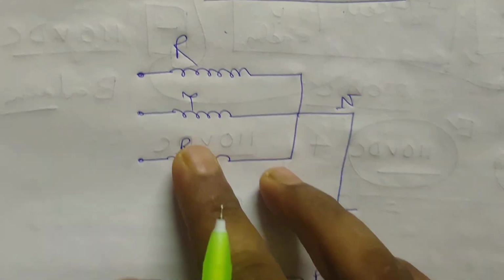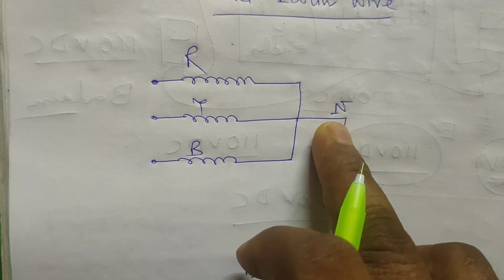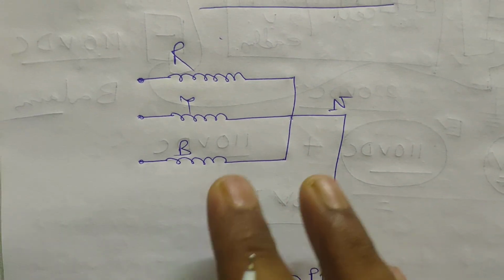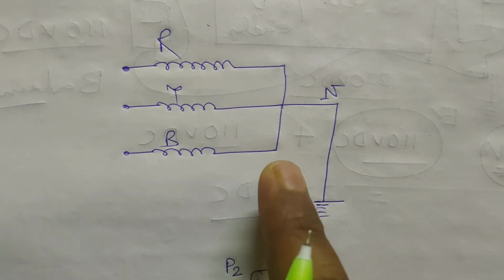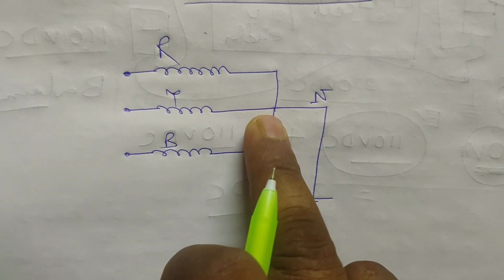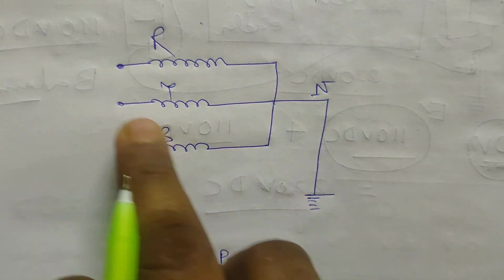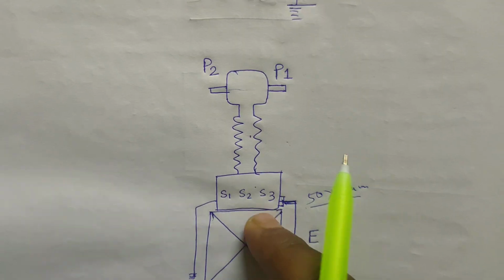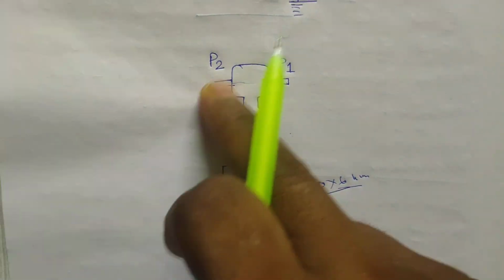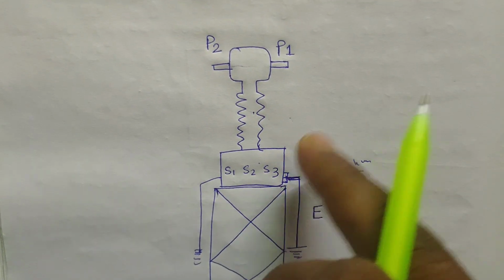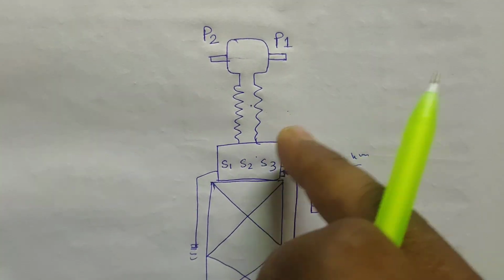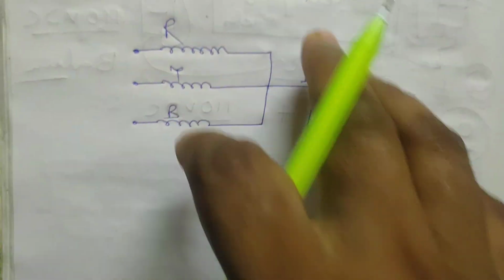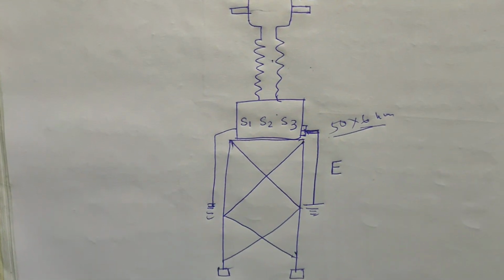So you understand what the neutral is. Neutral comes out from the transformer star point. It is used for the protection of transformers, or in the generator in the power plant for generating electricity, to balance the imbalance current of the three phases in case of the load terminal. And earthing is for the leakage current or the fault current. During a fault situation, this current passes through this earth point. So this is the difference between the neutral point and the earth point.